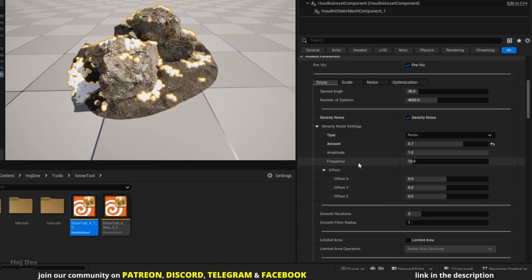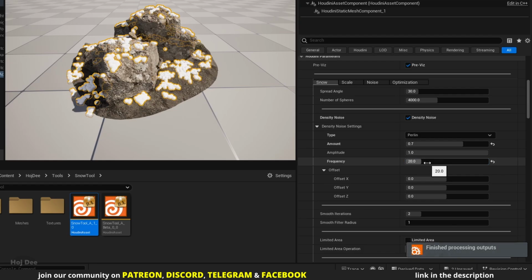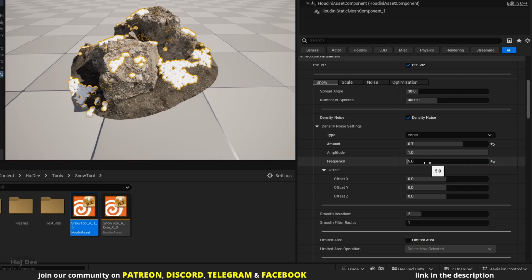Frequency controls the size of the noise. The higher the frequency, the smaller the size of the noise. It's like the tiling option in Unreal Materials. By default, it's set to 10 and it controls the frequency of the noise in all axes. If we set it to 20, this is the result. And if we set it to 5, this is the result. We can clearly see how the size of the noise pattern changes. Let's set it to 10 and continue.